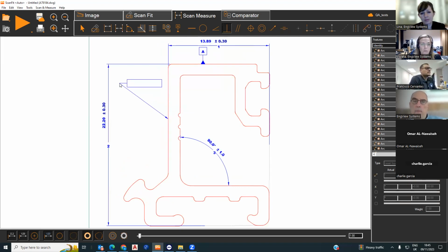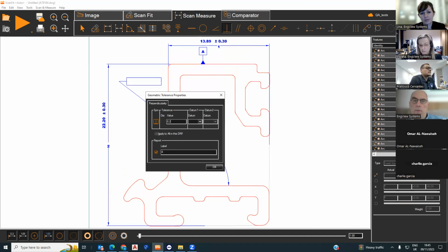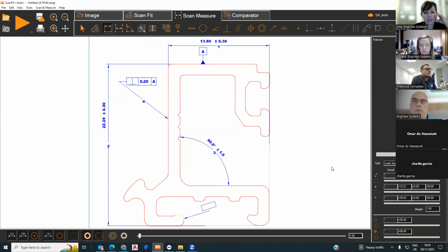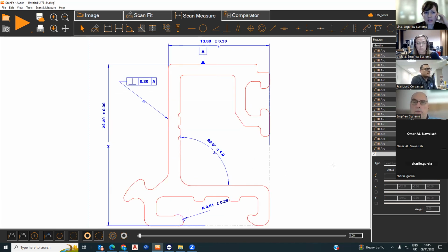Okay, it's very easy. This is the base. And the measurement template is prepared only once for each profile ID, for each die, and you can use it as many times as needed. And you can see that the measurement plan takes about 5 minutes to prepare.